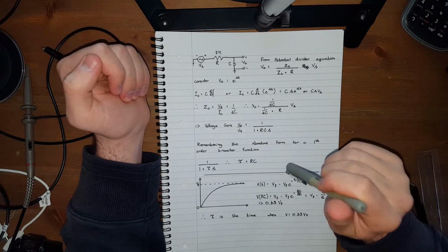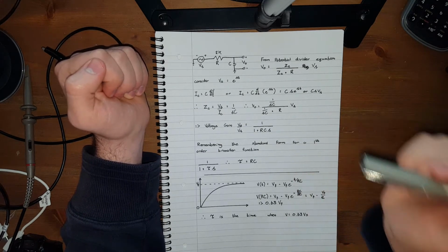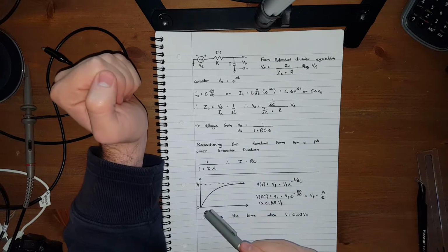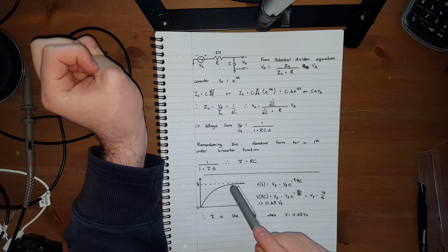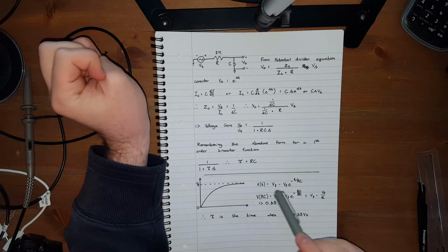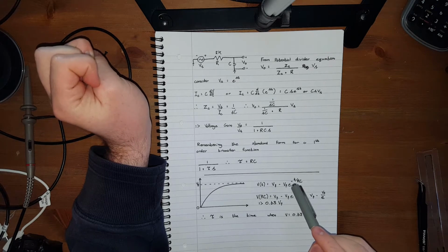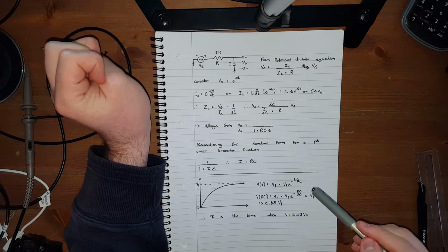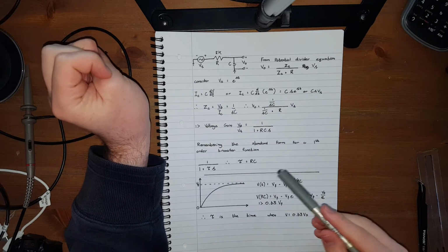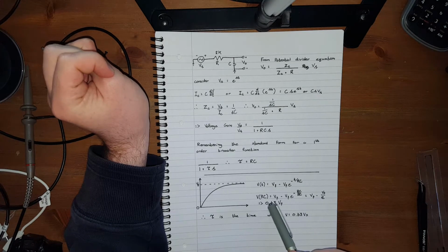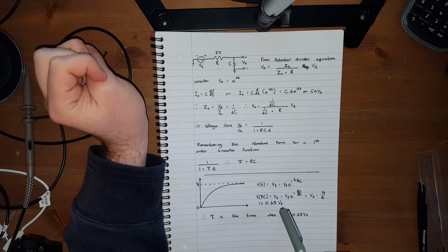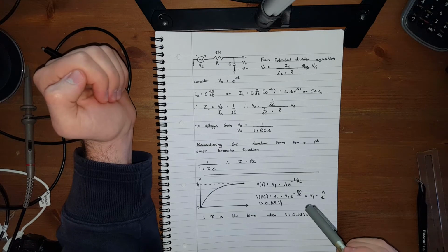So it's all about measuring what the time constant is using our oscilloscope. Now if we look at the voltage against time curve for a charging capacitor, it looks something like this. It has this equation: V final minus V final e to the minus t over RC. We've already established that our time constant is RC, so if we let t equal RC, we end up with VF minus VF over e, which simplifies to 0.63 times VF, or 63% of VF.